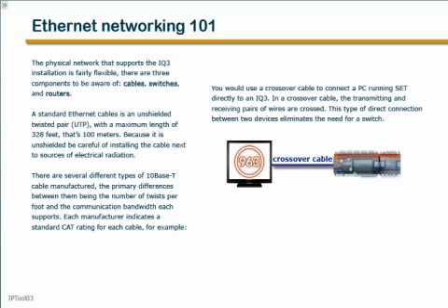You would use a crossover cable to connect a PC running SET directly to an IQ3. In a crossover cable, the transmitting and receiving pairs of wires are crossed. This type of direct connection between two devices eliminates the need for a switch.